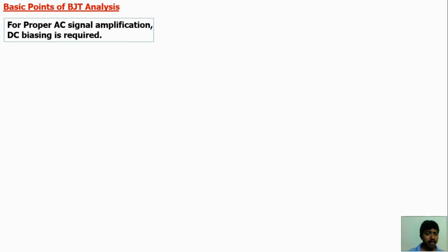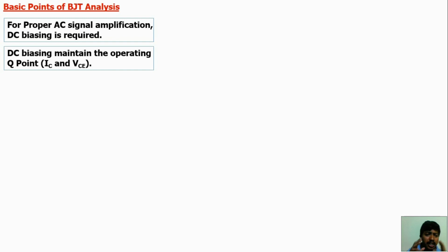We know that the BJT is mainly used for AC signal amplification. For proper AC signal amplification, DC biasing is required. Already we discussed the various DC biasing methods: fixed bias, voltage divider bias, collector feedback bias. All these concepts are discussed in a single video. The DC biasing maintains the operating point, the Q point, in the midpoint region. Q point means collector current versus collector to emitter voltage VCE.